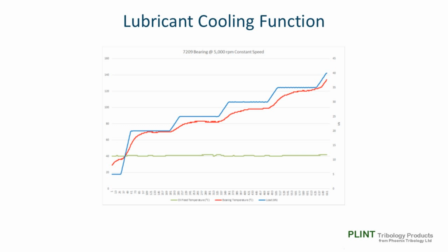This is an analogous problem to that created when overfilling a grease-lubricated bearing. The optimum fill is typically about 25% of the bearing free space, and overfilling the bearing with grease will often cause it to fail prematurely.